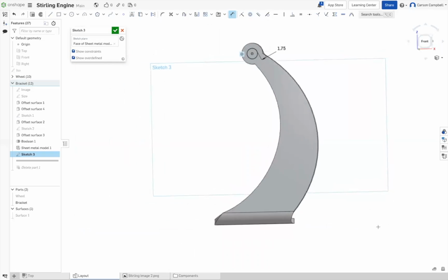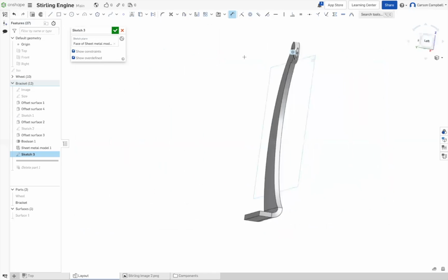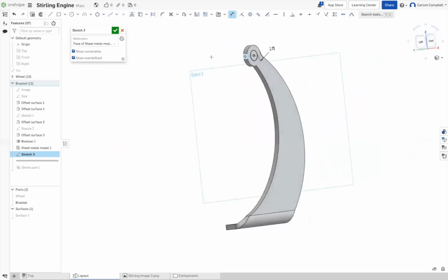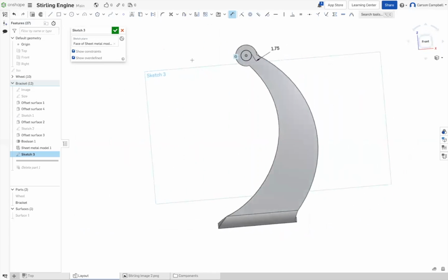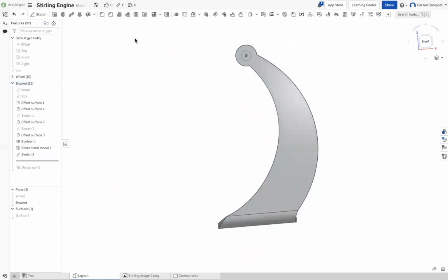Okay. I don't think that is your design intent because typically the outer edge is who cares, but that hole is very precise. So you want to delete that 1.7 and you want to go back to your other dimension, right? You don't want that to be a crappy hole. You want that hole to have a pretty tight tolerance on it. And that's fine, 3.5. Type in 3.2. And say okay. Oops. And 3.2 is a clearance hole for an M3 bolt.